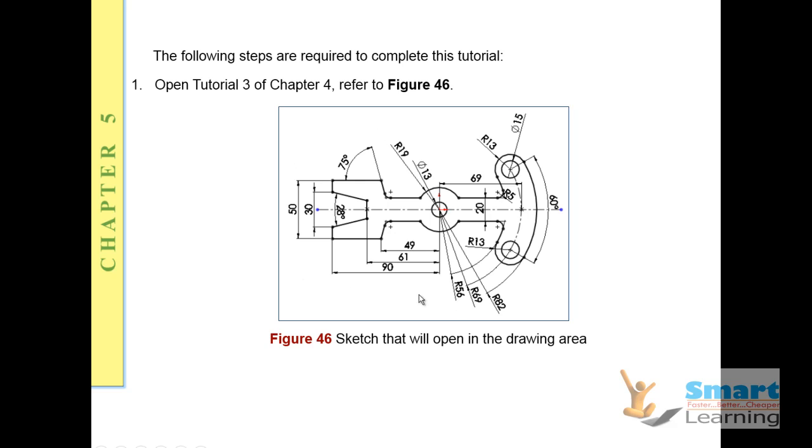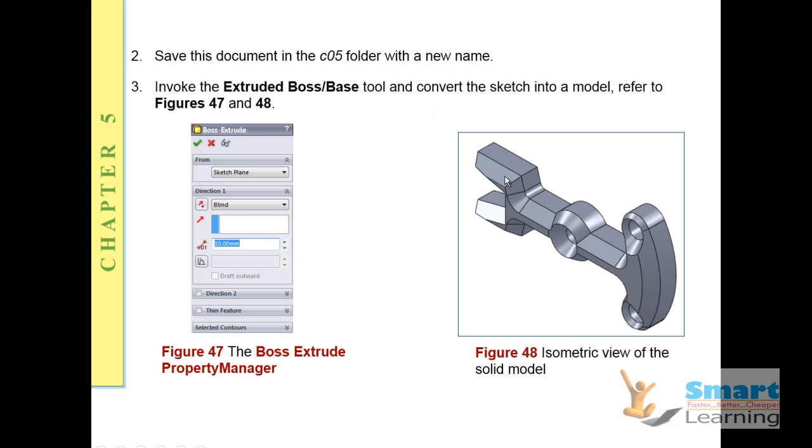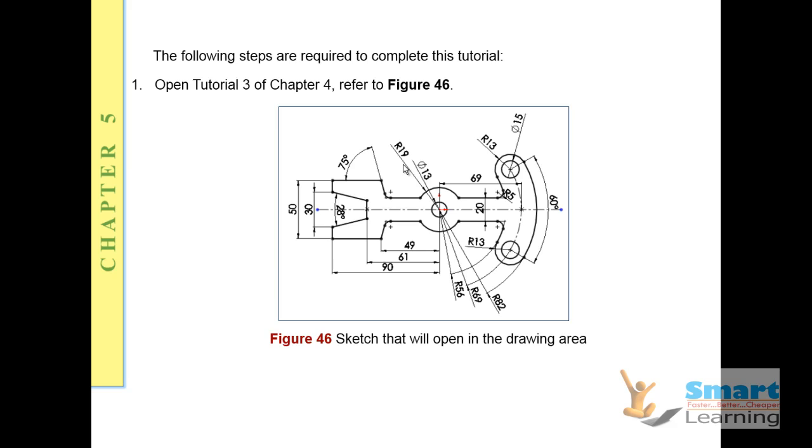So you need to have this as your sketch, and once you capture this sketch, you can directly apply the extrusion in the required directions. And in this particular first direction you have the draft, and in the second direction you have the normal extrusion. So how to control this and apply that, I will show you in this particular session. So let us start with this particular sketch.